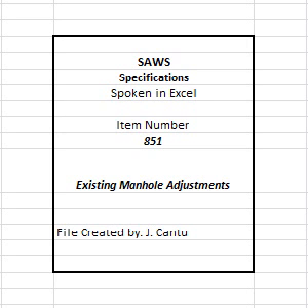6. Contractor shall take all necessary measures to prevent damage to existing or new rings, covers, or cones from equipment and materials used in, or taken through, the work area. If an existing or new manhole cover, ring, or cone is damaged by the contractor, it shall be replaced, as directed by the inspector, by the contractor at his own expense within 3 working days.